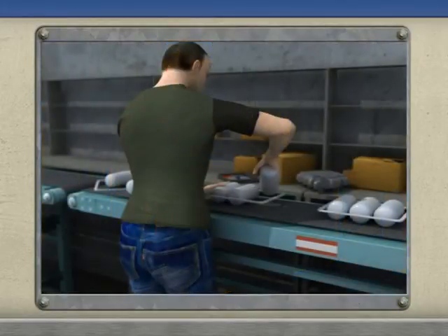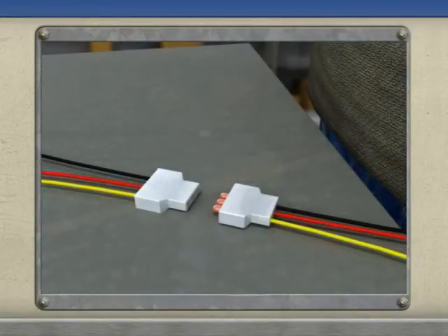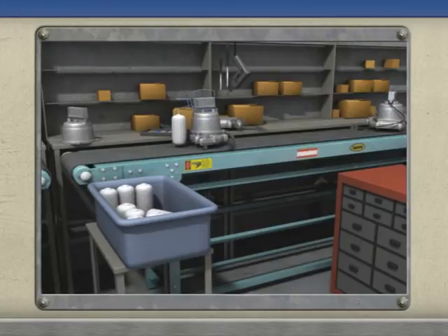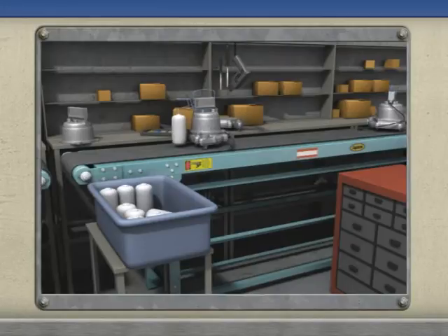Changing the process or product to reduce worker exposures to risk factors. Examples of this include maintaining plastic molds to reduce the need for the tedious manual removal of excess flashing, or using Easy Connect electrical terminals during assembly to reduce the required manual forces. Modifying how parts and materials are presented and accessed. This can be as simple as tilting or adjusting the height of frequently accessed parts or material bins. Changing workstation layout, which might include using height-adjustable workbenches or locating tools and materials within short-reaching distances.